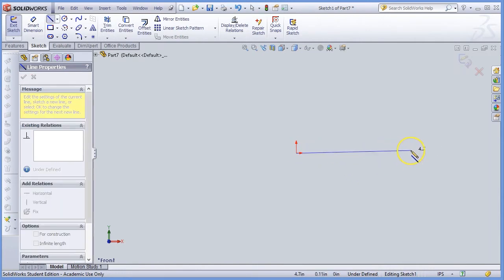We're going to draw a roughly 4-inch by 2.5 or 3-inch tall, sort of 3-finned comb. And you'll notice you're getting little tool hints, like right here I've got a vertical yellow line. That just means that it's setting a relationship that this line is vertical.